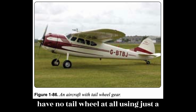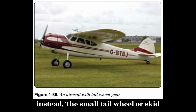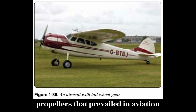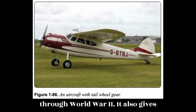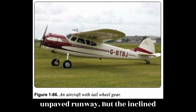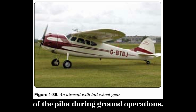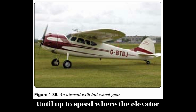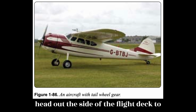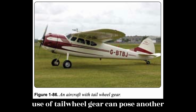Other conventional gear have no tail wheel at all, using just a steel skid plate under the aft fuselage instead. The small tail wheel or skid plate allows the fuselage to incline, thus giving clearance for the long propellers that prevailed in aviation through World War II. It also gives greater clearance between the propeller and loose debris when operating on an unpaved runway. But the inclined fuselage blocks the straight-ahead vision of the pilot during ground operations. Until up to speed where the elevator becomes effective to lift the tail wheel off the ground, the pilot must lean his head out the side of the flight deck to see directly ahead of the aircraft. The use of tail wheel gear can pose another difficulty.